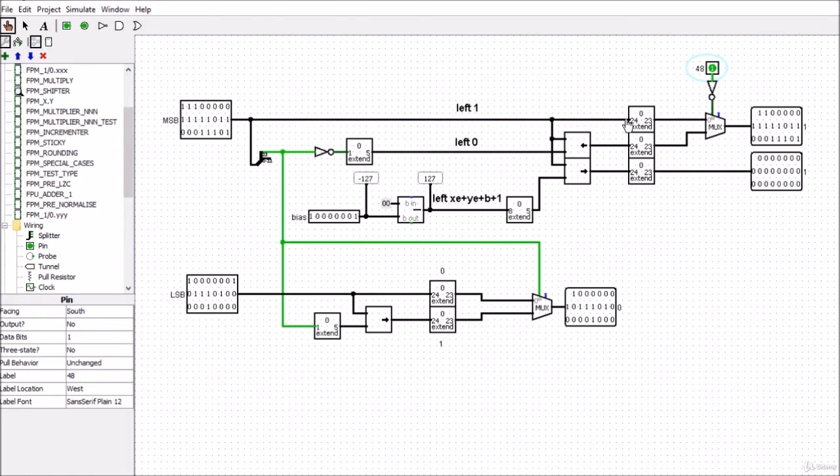And when it chooses this route, what we do with this route is that we simply cut off the most significant bit. So when we cut off that most significant bit, we're going to be left with our 23 bits, and we're going to have the correct mantissa, which is just going to start out with 1, 1. There you go, that bit's disappeared, we've got the 1, 1. So it's just a neat little way of killing two birds with one stone. We get rid of the 24th bit of the extension, and we in effect get the correct mantissa value. So that's one route that it can take.